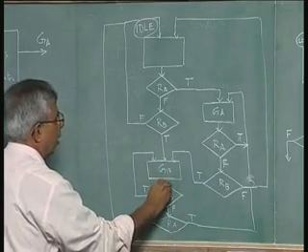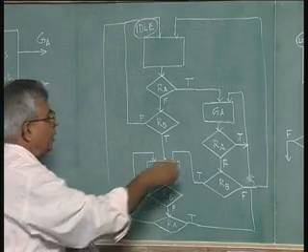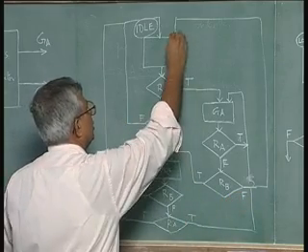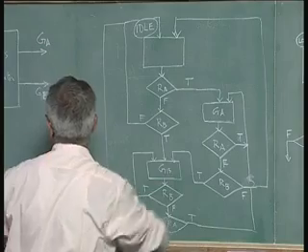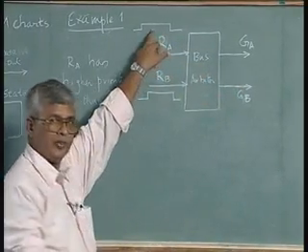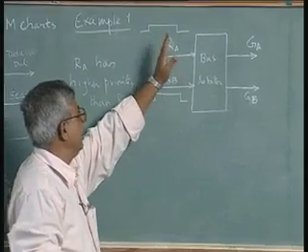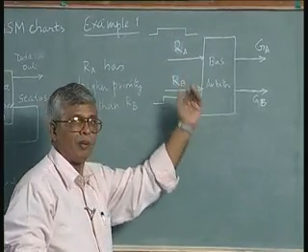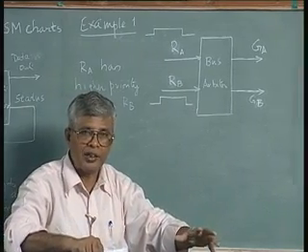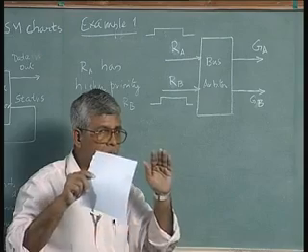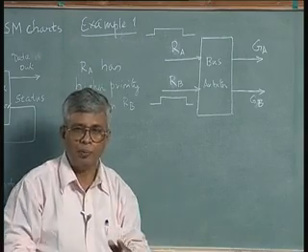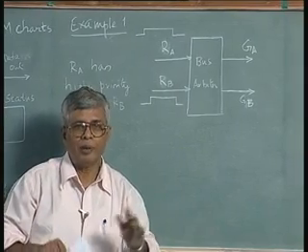This is the ASM. We will have to map it into hardware, which we will do in my next lecture. This is how you define the system: input signals, output signals, the conditions and specifications will be very properly written, like what happens if RA comes first, RB comes first, and what will happen if RB comes in between RA. All those will be very clearly defined. Problem specification is about 40% of the problem, ASM drawing is another 50%, and the rest is 10% or maybe 20%.